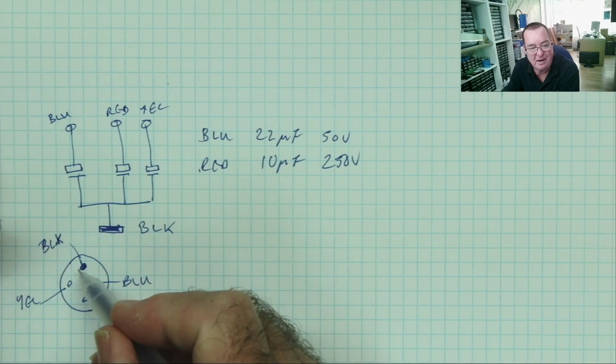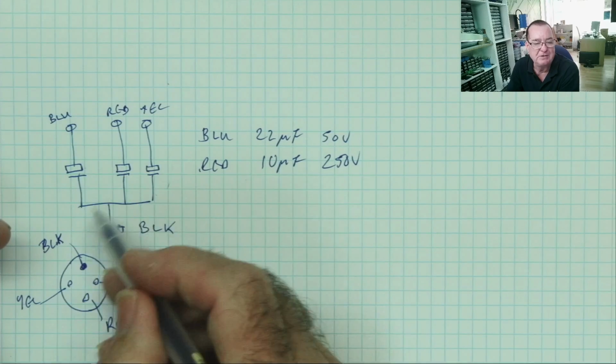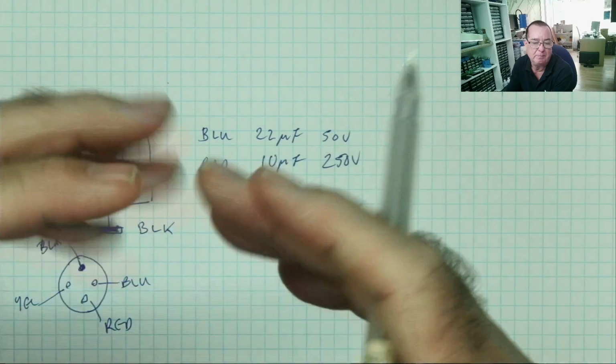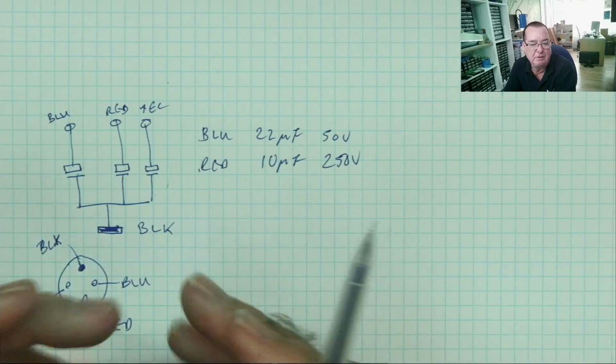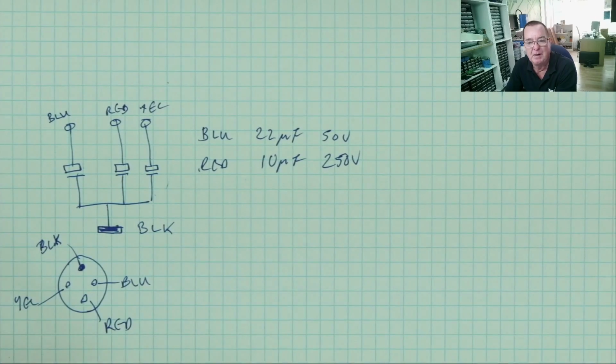And then inside you can actually solder your 3 modern capacitors across these pins, put it all back together, bit of resin glue, stick the top back in again, and it'll look like the original. It'll still be the original case with the values on, but inside will be new capacitors. So just a little hint if you're working on that sort of stuff.